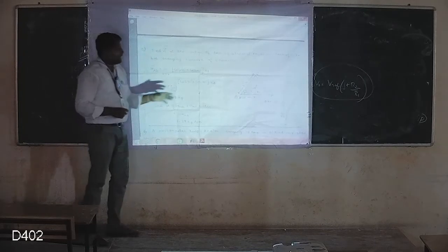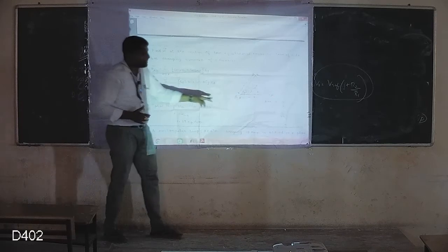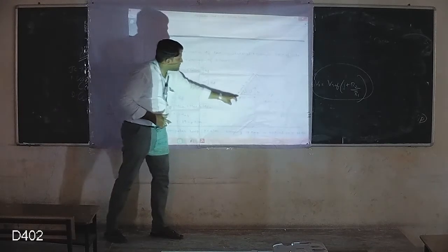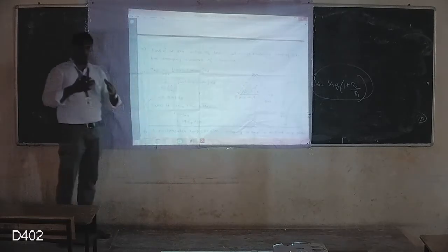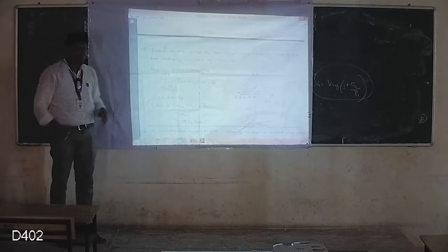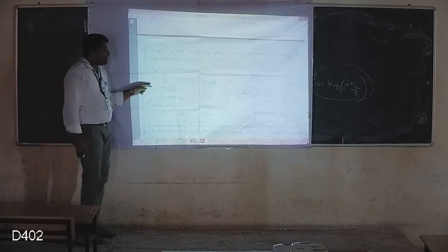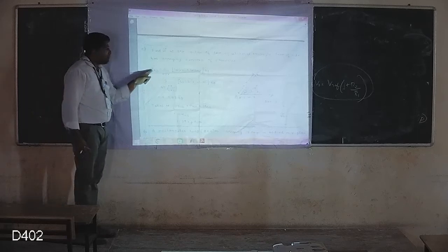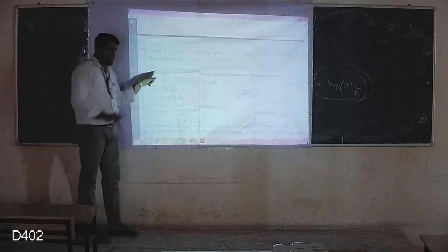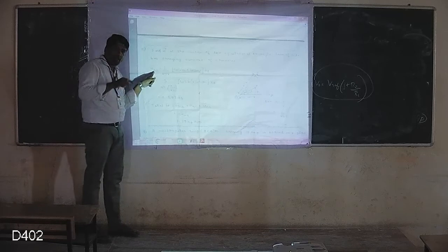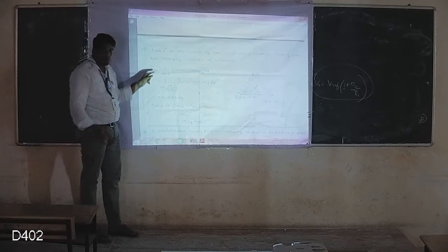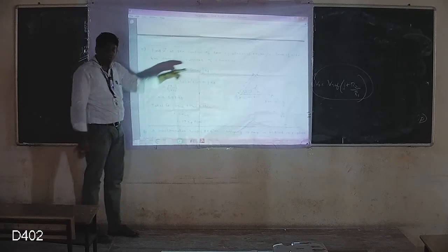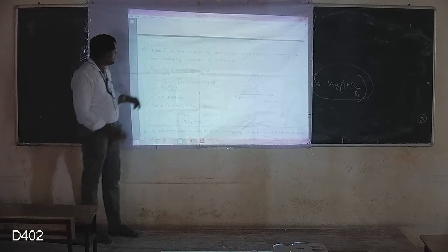We can think of the problem such that it is one finite conductor, a second finite conductor, and a third finite conductor. So there are 3 finite conductors joined to form a triangle, and with that scenario, I will evaluate only one, AB. If AB is found, BC and CA will be the same, and therefore the total H vector is equal to the addition of all 3. All 3 will be the same because it is an equilateral triangle, and therefore we are evaluating H_AB.